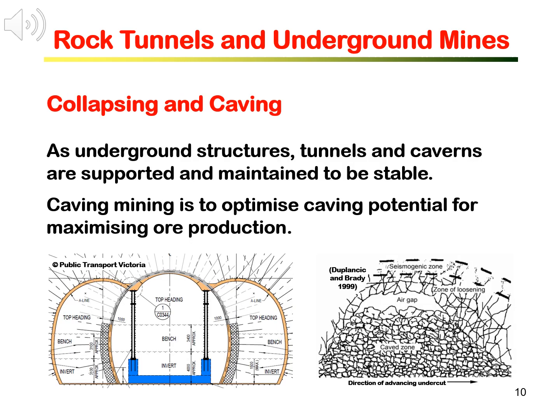In block caving mining, we utilize controlled rock mass collapsing under gravity to remove all rocks. For tunnels and caverns, our effort is to maintain the stability of the opening through shape optimization, rock reinforcement and support. This is what we are doing for rock caverns, shown on the left.